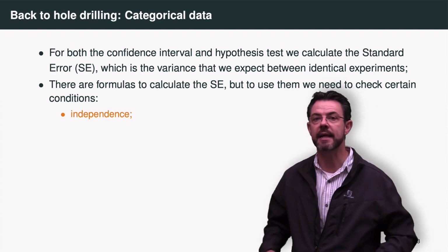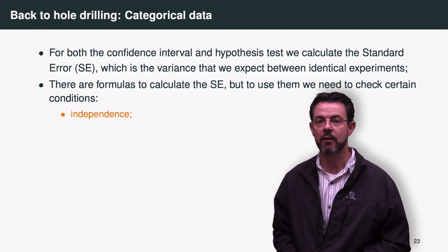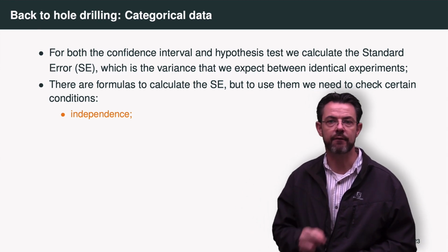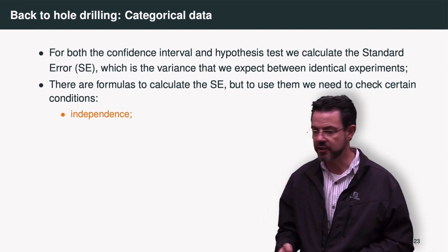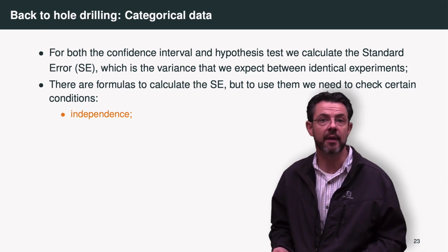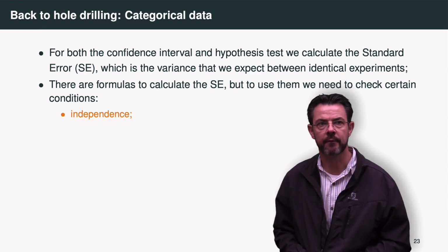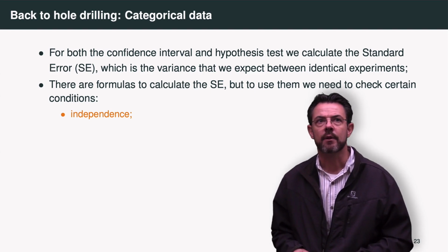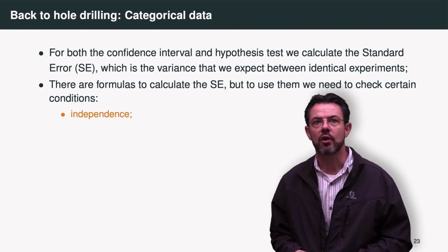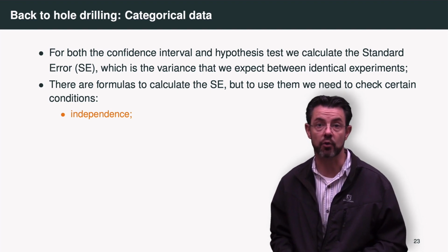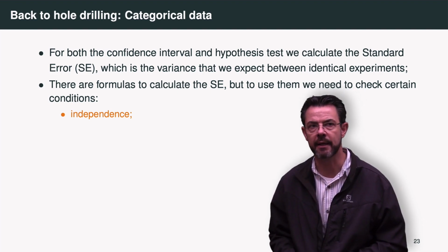The first one is independence. With that we mean the samples that you've taken, are they independent from one another? If we just have 30 pieces of material and we drill a hole in each, we can claim that they are independent from one another. But for example, with something like temperature, it becomes a lot harder to actually prove independence or to show that measurements are actually independent.